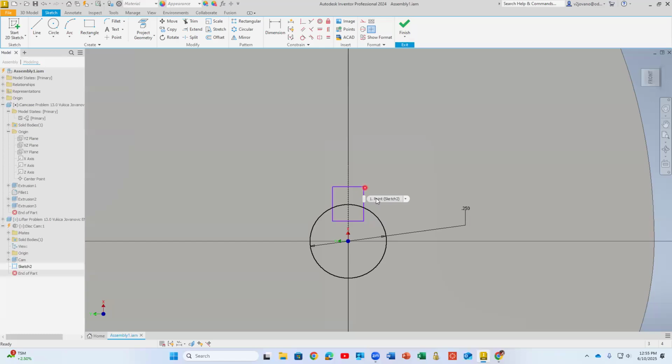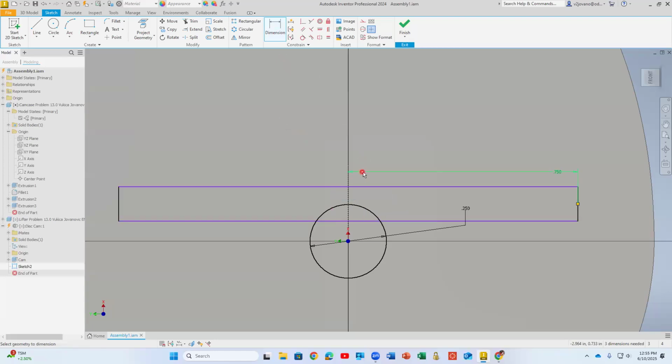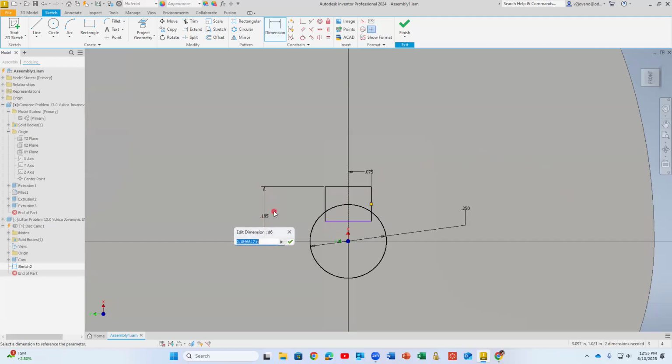So you see it is, because they're dimensioning twice, 0.75, and I can just dimension 1 time, and now I don't have to do it 2 times. Oh, 0.075. See, no, but it's parametric and we can change it anytime. So you see here, 0.188. There you go. So, and you know, really, when I want to extrude, I don't even need to cut this.